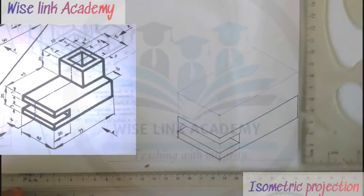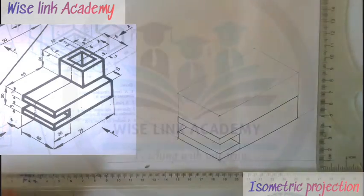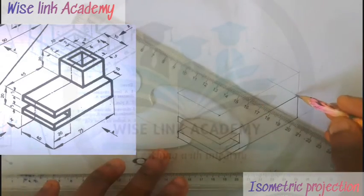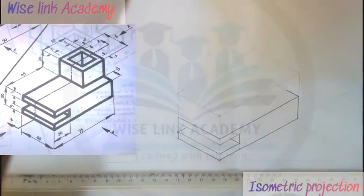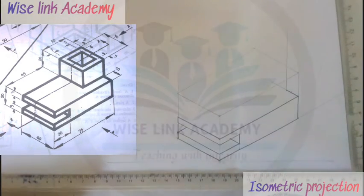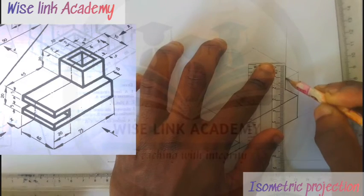So what will be my next task now is to produce out the square, or perhaps the small box up higher. But before that, observe that if I take this part inward, I have a distance of what? 10. So I'll measure 10 millimeters, which is equivalent to 1 centimeter, taking it from here to here. Having taken that, I will take my set square, project upward this way. This point I projected upward, I will measure out 20 from this point. From here to here is 20. So you can see 20.